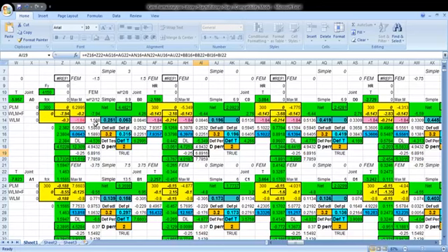So what we got? We got this value for beam and column. We got this value and this value and this value for these three members. So one cycle of this A0 joint is over, and first cycle for B0 joint is over. Now we have to go this way. We cannot go vertically immediately. We have to go this way, and we have to reach a joint C0.